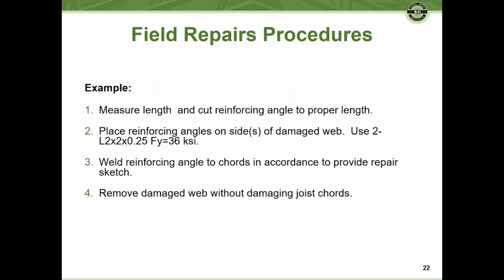Also, field repair procedures, kind of a step-by-step of what you're expecting the guys in the field to do. As an example, if we were going to be adding additional webs to a joist, this could be used. Number one, measure length and cut reinforcement angle to proper length. If that's going to be done in the field, that's a good thing to have them do first.